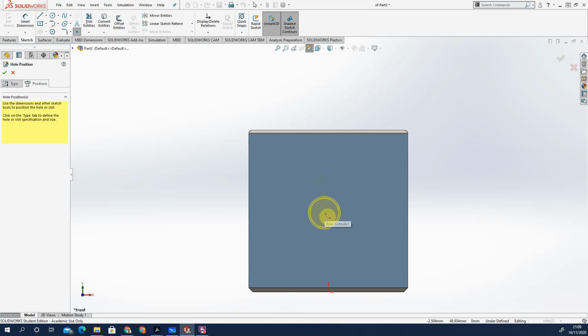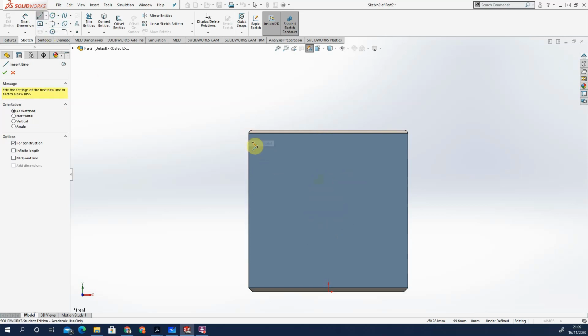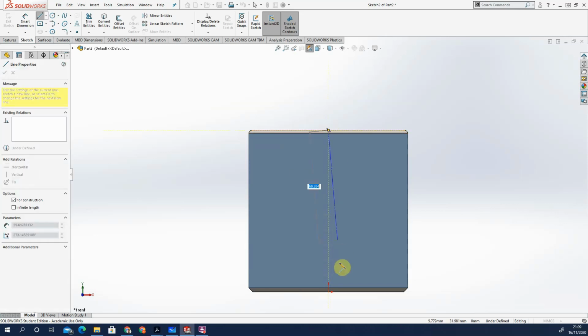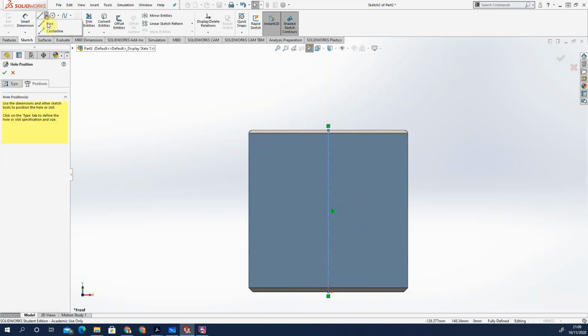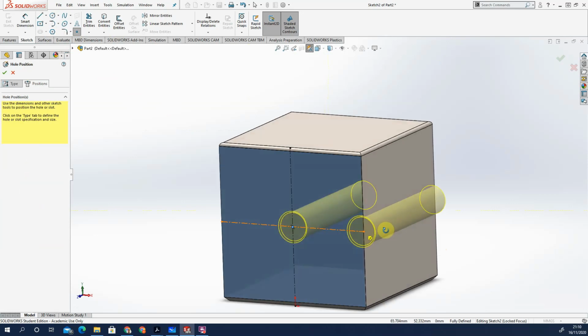So again, I could do this in one of two ways. I could make it a centre line, but I've actually removed the corners, so it'd be quite hard to work out where my edges were. As per my sides, I've got my midpoints, which I could then run centre lines through. So SolidWorks will allow you to run centre lines just matching up to the components. Just going to drop down again, another centre line, latch onto my midpoints, like so. Then I can just put a point on, and that'll tell the system where I want my part.